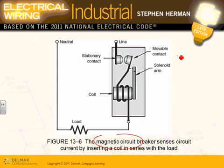The way this works, if this is a 20 amp breaker, and you have a short circuit right here, a ground fault, going to the ground. So now you're pulling out of a 20 amp, let's just say 300 amps momentarily. Can you guys see that? You're pulling 300 amps. Now the current is going to go through the coils, right? When it goes through the coils, it's going to create a magnetic field that pushes this solenoid arm, that moves the solenoid arm away and opens the circuit breaker.